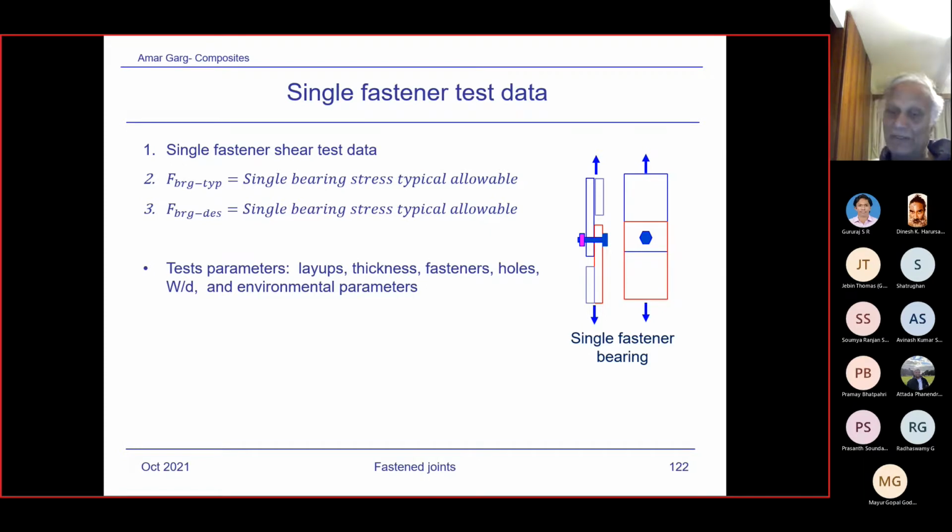Then it goes like one element is showing very high and the next element is showing very low. Somehow FEM is showing a stress gradient. Really, we feel it should not exist so much. Suddenly stresses can't drop so much. But again, then we consider some kind of averaging process.